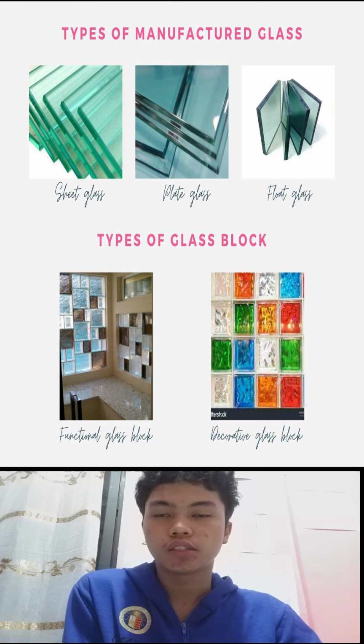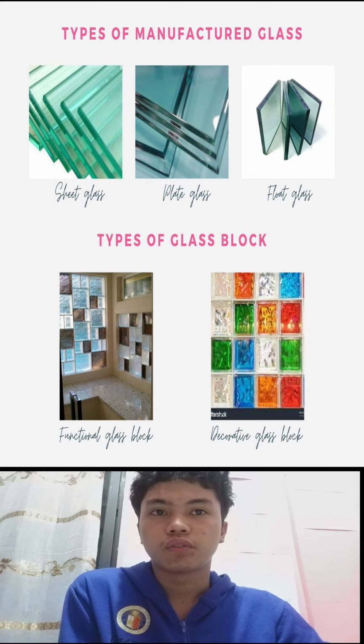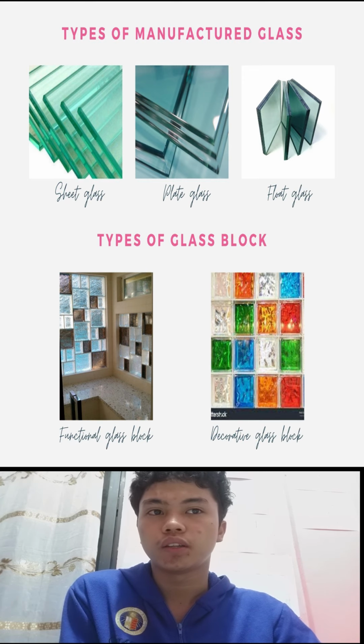As the ribbon of glass passes through the float bath, the heat is reduced until the glass is sufficiently hard to be fed on the rollers of the lehr without marking the undersurface. After leaving the lehr, the glass is cut into long lengths. This process is suitable for thicknesses of 1/8, 3/16, and 1/4 inches.